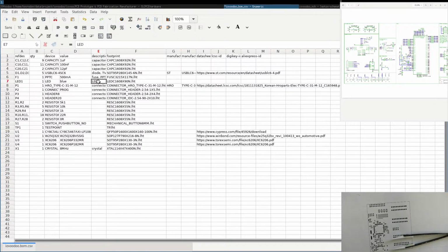For example, if it's an LED, which kind of LED, if it's a crystal. And this is not, I always call them crystal resonators. They are not resonators. Resonators have an active circuit, so they have VCC and ground going to them. This doesn't. This has only 2 pins, so it's a quartz crystal, and not a crystal resonator, and not a crystal oscillator. Quartz crystal only.